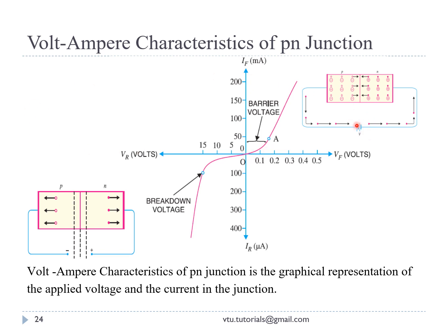Hence there is no current flow at the external voltage equal to 0. So as we now move on with application of forward voltage, at zero external voltage, the voltage is 0 and also the current is 0. Next we move to the forward biased curve.